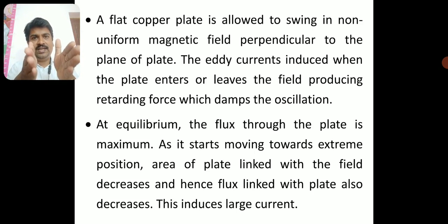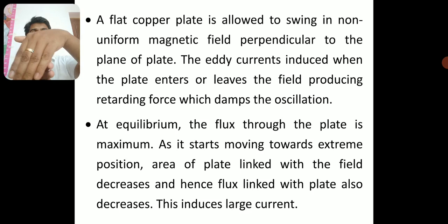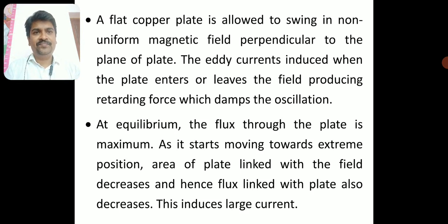Now this is the area of the magnetic field. When this plate enters the field, eddy current is induced. When it leaves the field, again the eddy current is induced. So this eddy current will produce a retarding force which damps the oscillation.